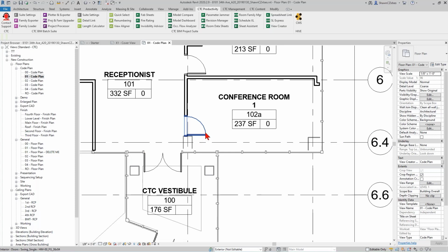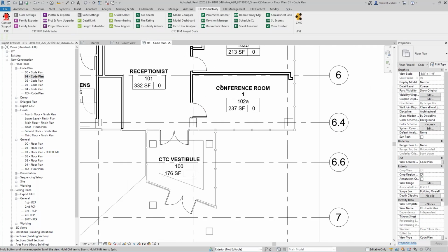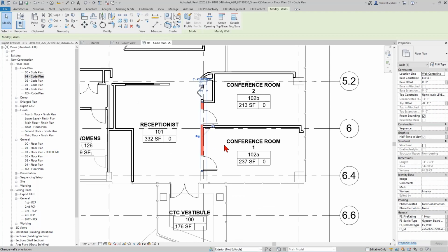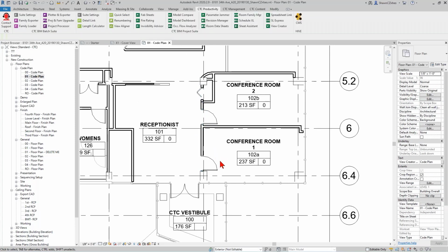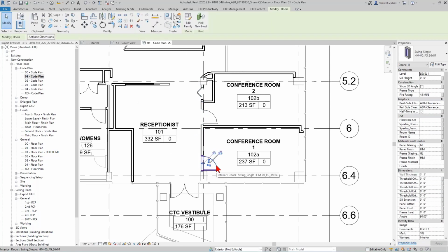I have to know this, and I have to go door by door by door through my project and look at all my walls and understand what's the fire rated walls, what aren't, make sure my doors have the correct ratings. And in Revit, natively, there is no way to do this. Stock core vanilla Revit doesn't know how to take my doors and make them read a specific property from the wall, and do something with that. Can't write a formula for it in Revit.